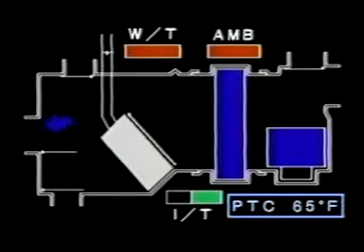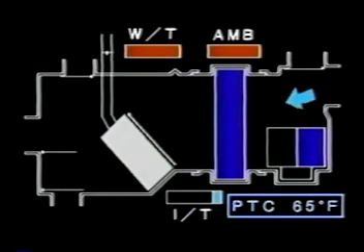As the in-vehicle temperature approaches the set temperature, the air volume gradually decreases. Finally, the in-vehicle temperature reaches the set temperature, and the air volume will be decreased.